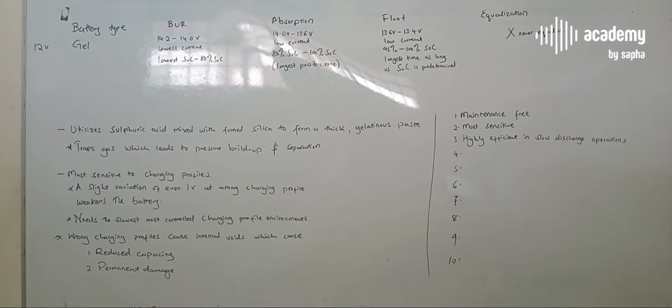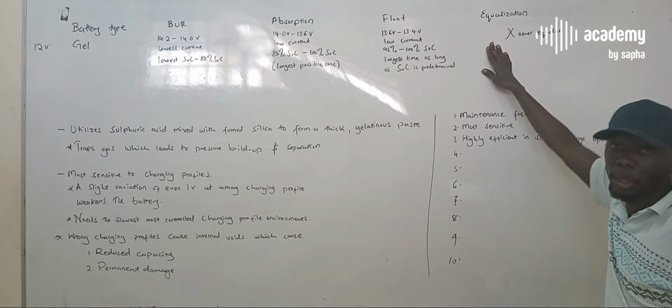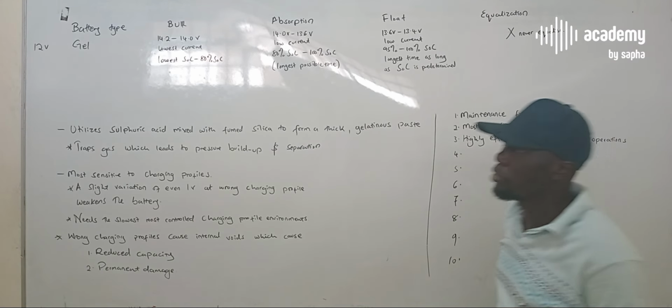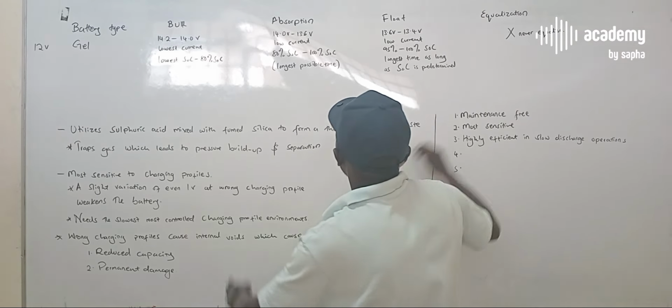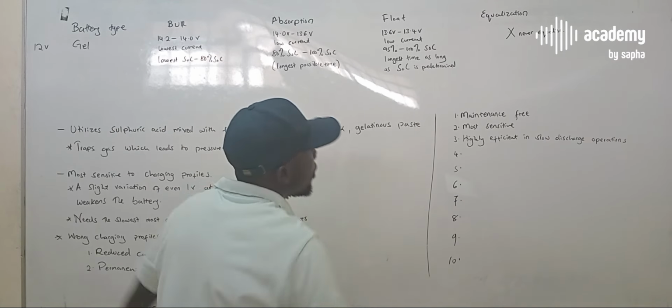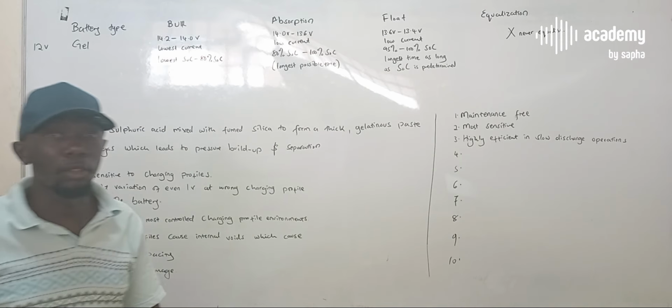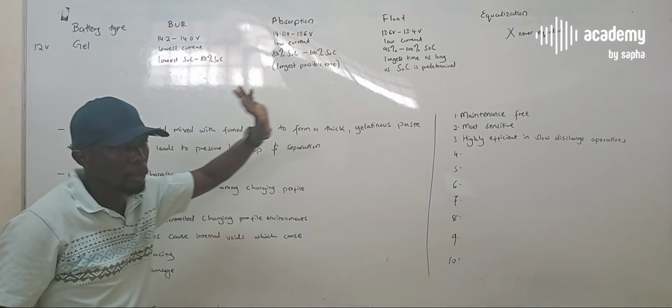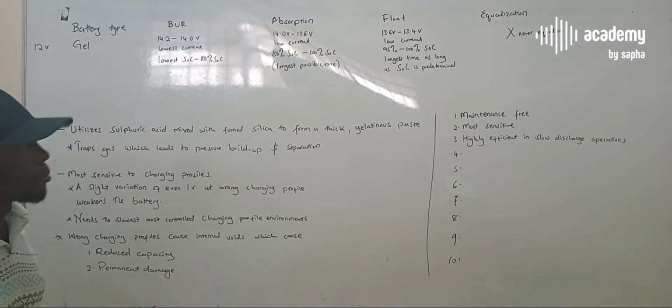So for this system, we do not have any equalization. So here we avoid equalization. Once you install it and you maintain this, if your inverter and battery have got a communication protocol that can maintain these charging stages, never do equalization for a gel battery.